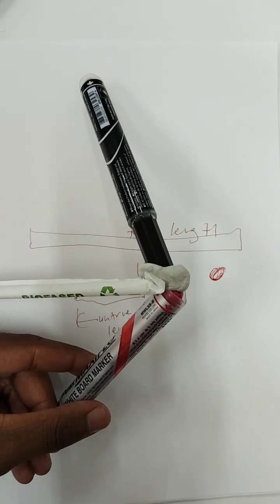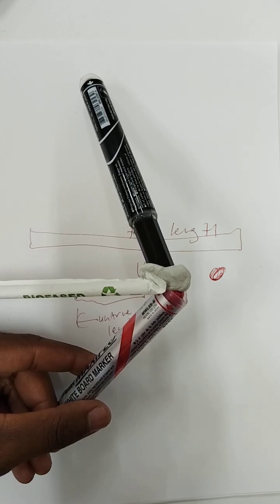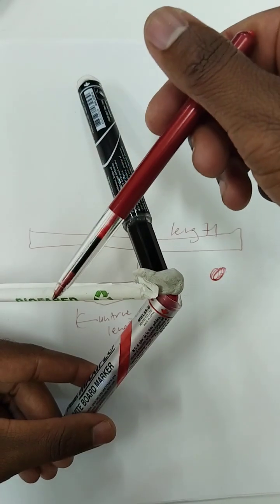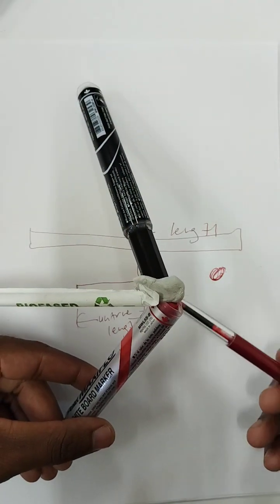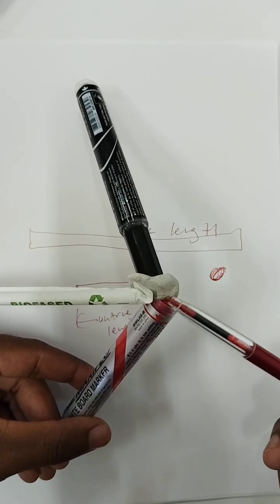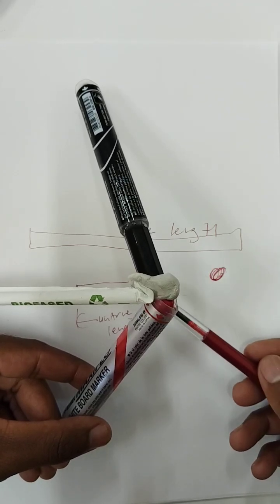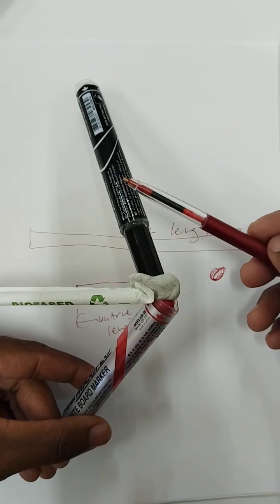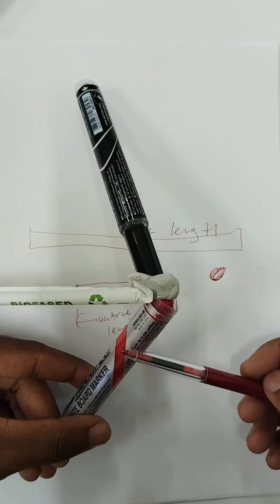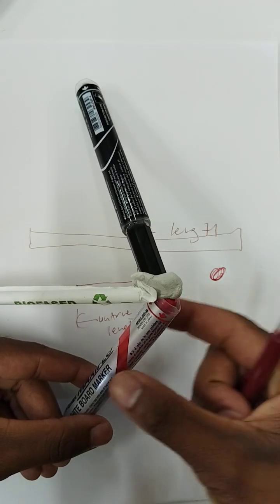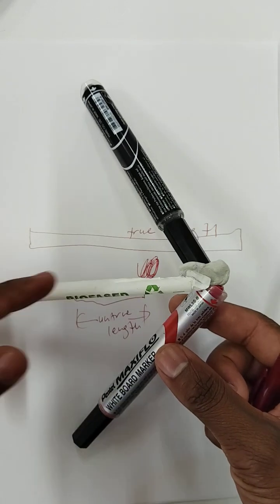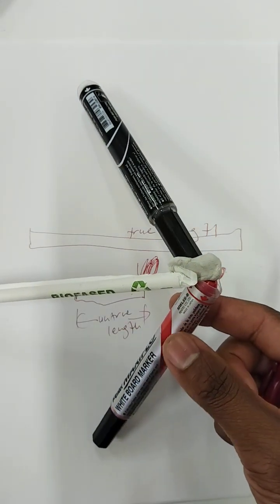So our main goal here is to determine the force in each leg as well as in the backstay. These are the legs that we're talking about. This is the backstay. As the load will be supported here, that load is going to push downward. So this marker will have to resist, apply force in opposite direction. So even this one, as the load pulls down, this white member will be stretched.